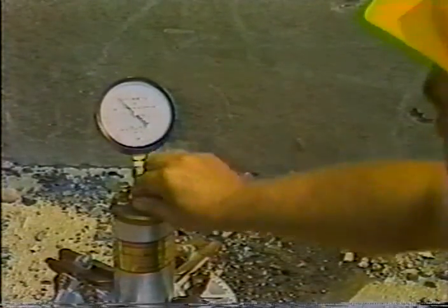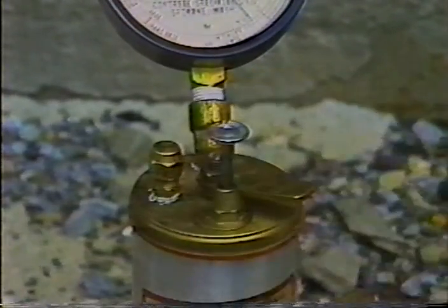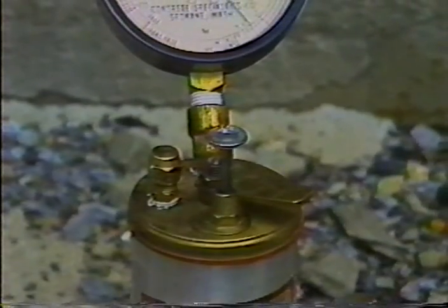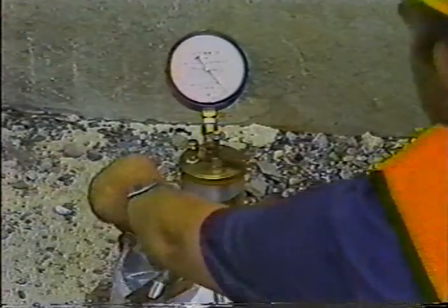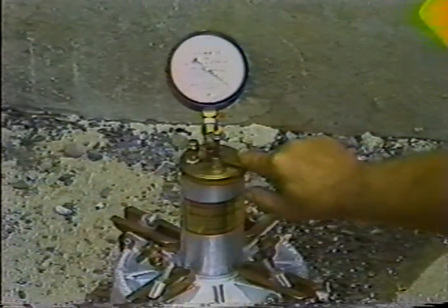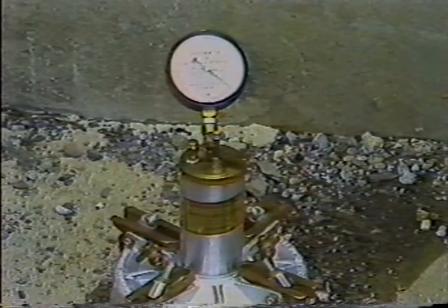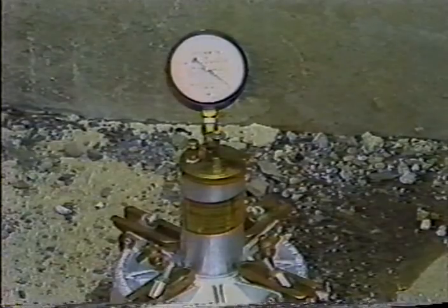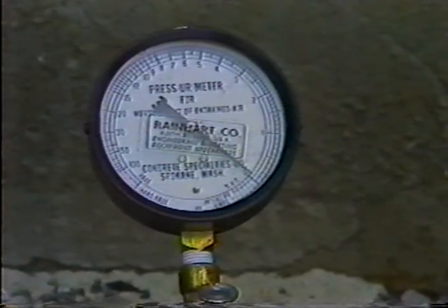Pump air to a little beyond the initial pressure line. Wait a few seconds and then stabilize the gauge hand at the initial pressure line by pumping or bleeding off as needed. Now close both petcocks and immediately press down on the thumb lever. The air is exhausted into the base. Wait a bit for the hand to stabilize. The gauge should read 0%. If it doesn't, run another test.